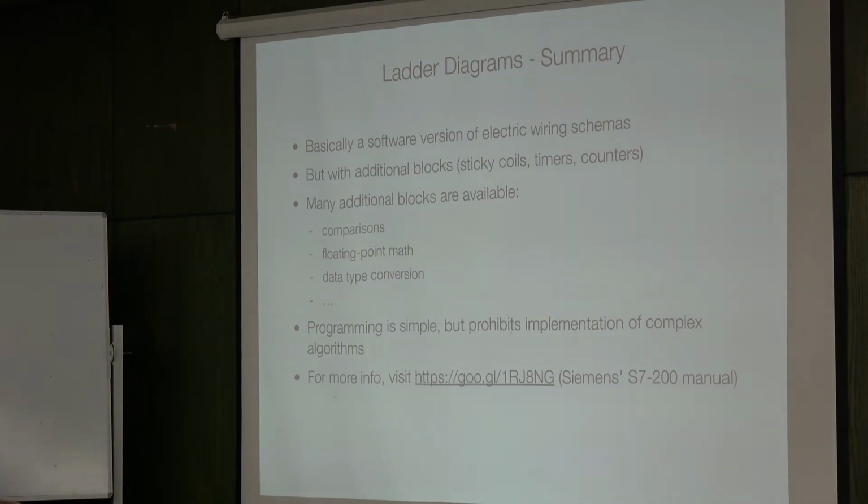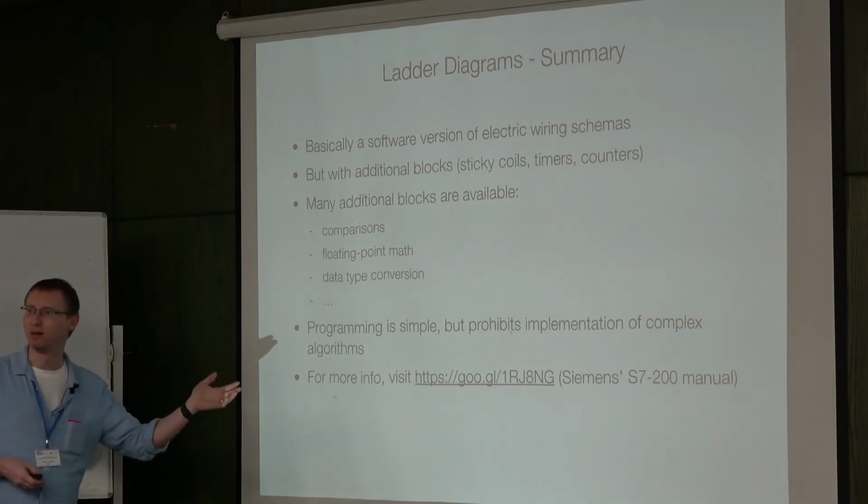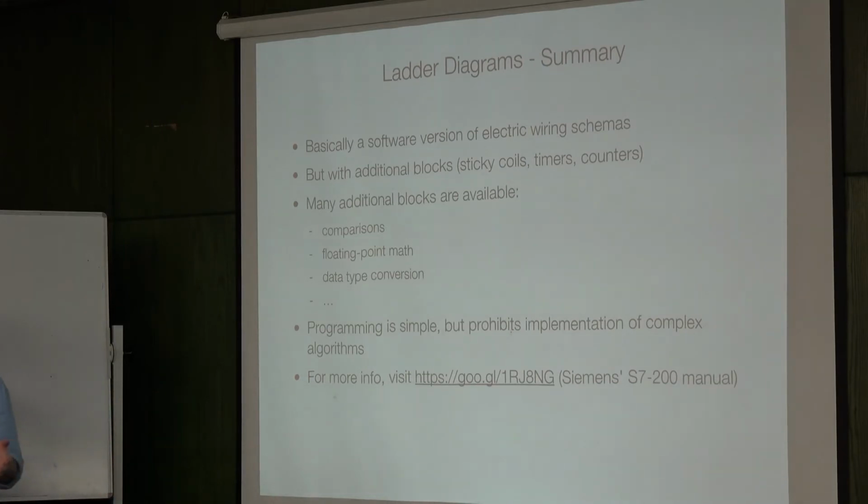But if you consider ladder logic to be confusing by this time, and we were only doing very simple logic control, then doing, for instance, floating point mathematics is maybe even more inconvenient than those simple things. Bottom line is, we have seen it. It's such a simple language, and it requires us to think so far ahead that probably we cannot implement anything more complex than some simple logic, maybe PIs, PIDs, maybe LQRs, but that's pretty much it.